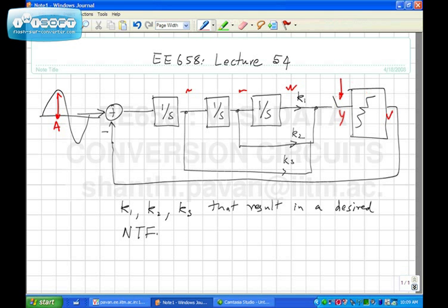So this signal Y of n is a discrete time signal. It will be the sampled version of the input plus, see, the negative feedback loop is going to make the signal component of this equal to the input. And on top of the signal component, there is going to be some shaped quantization noise riding. So if you look at the waveform here, it will be signal plus shaped quantization noise. It's NTF of Z minus 1 actually.